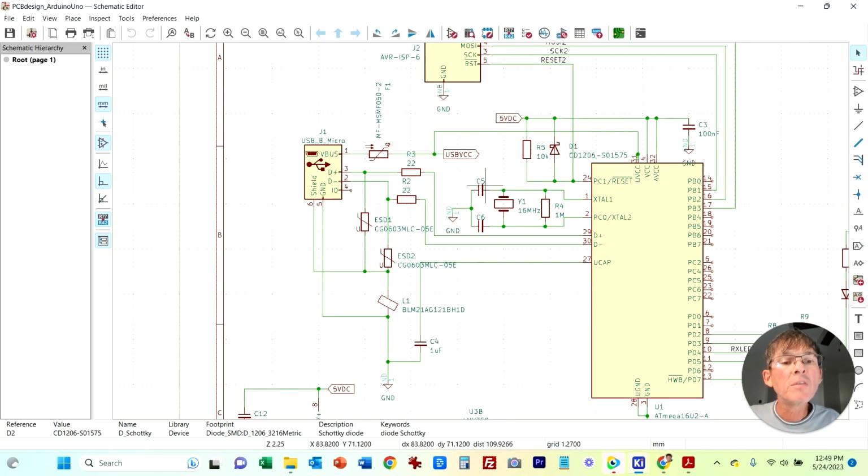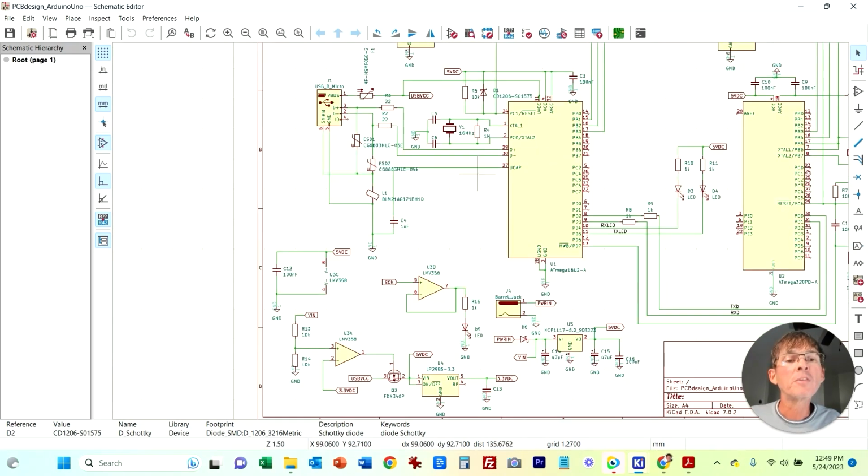We have C5 and C6. And yeah, C5, C6. Let's go ahead and place it. We still have to set the value of these. So we'll have to pull up the data sheet for the crystal, and it will tell you what capacitance these need to be set to. But I'm using just a standard 0603, so you don't technically have to do it because you can decide later what the capacitance will be as long as it fits in the 0603 package, which you'll be able to get any capacitor size that will fit in that package, the 0603, so 5 and 6.